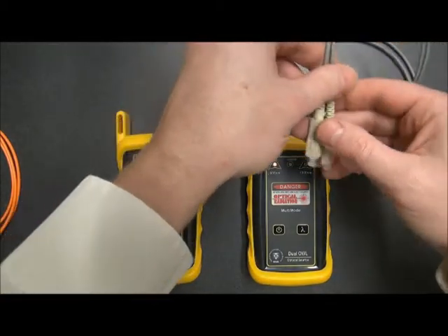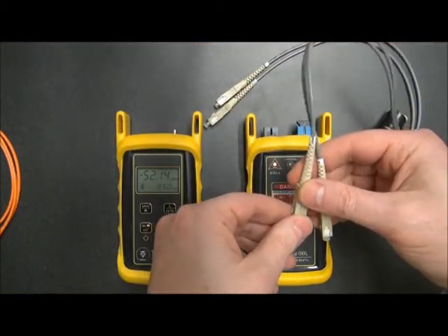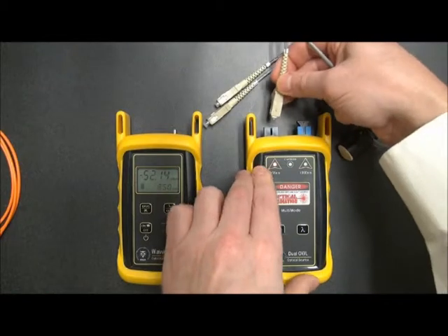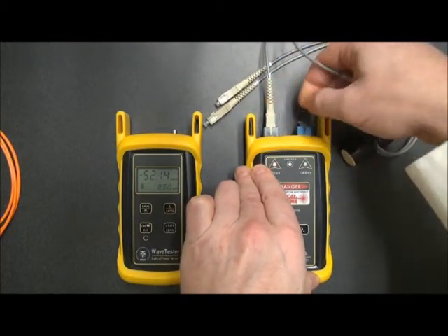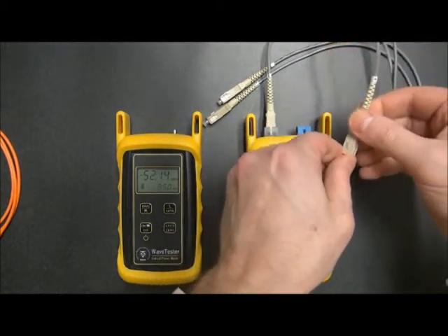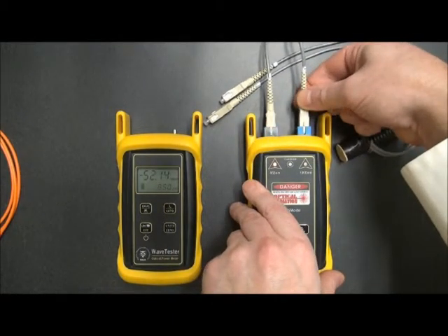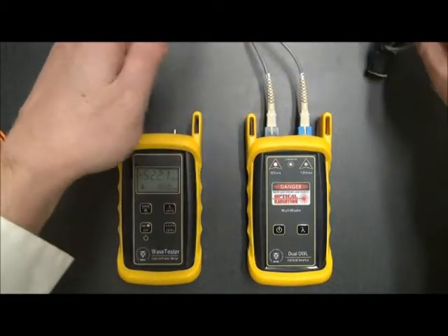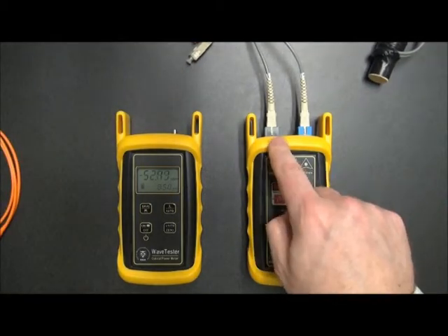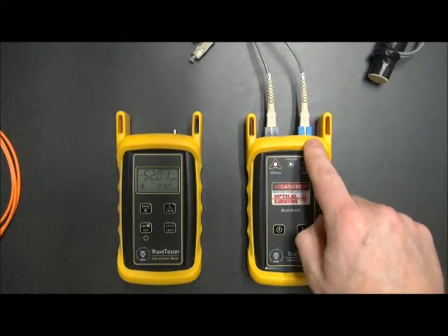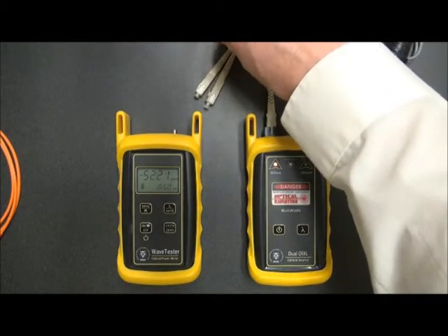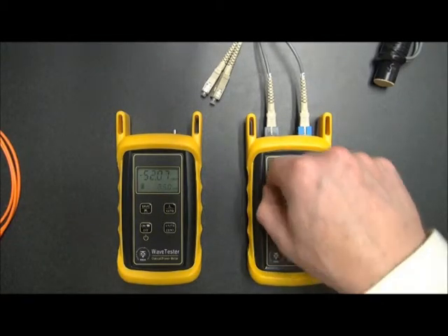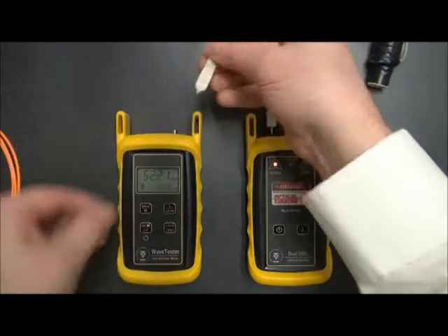The next thing we need to do is to measure these reference cables. These are the cables we're going to be using for zeroing. And since we have the dual owl here, we might as well connect both sides of this duplex cable to the different ports here. Okay. Now, once we have this connected, you can see we have a cable connected to 850 and one to 1300. They will correspond with the two different ends over here. So first thing is, since 850 nanometer is already selected, we find the 850 nanometer reference cable and we plug it in here.